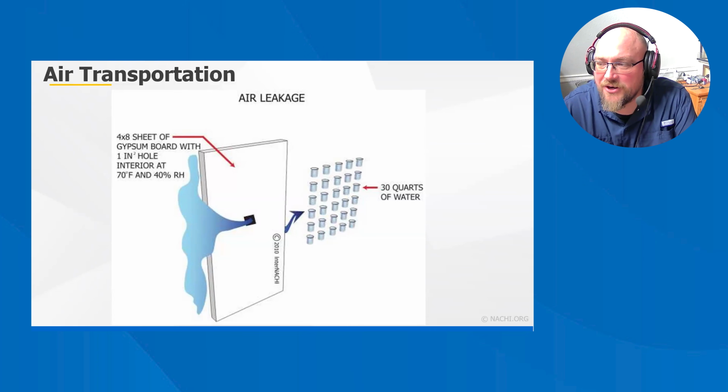Moisture transfer by air currents is very fast, in the range of several hundred cubic feet of air per minute. Thus, to control air movement, a house should have any unintended air paths, holes, gaps, cracks, and separations carefully and permanently sealed by a practice referred to in this course as air sealing. Diffusion through materials is a much slower process. Most common building materials slow moisture diffusion to a large degree, although they can never stop it completely.